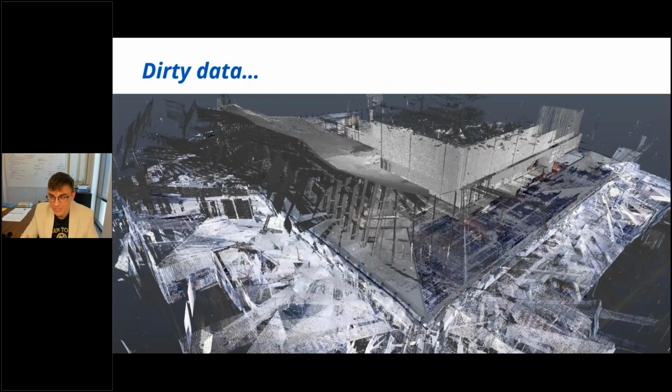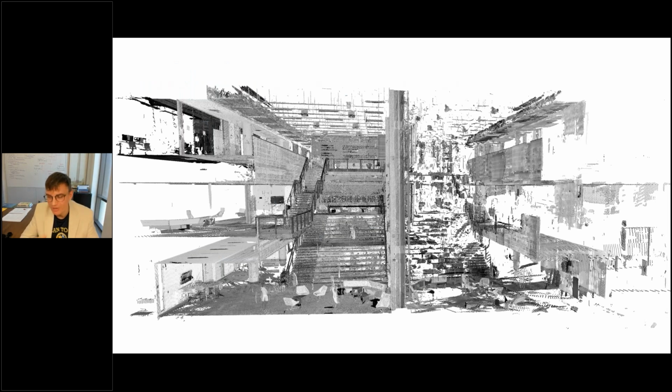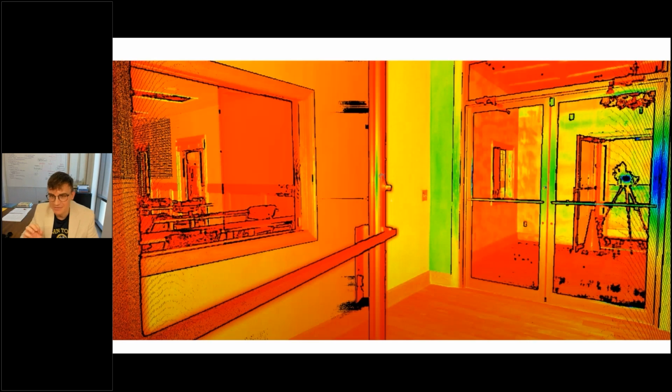If the client will be using the point cloud, you should probably spend more time cleaning it so that it's presentable. Certain kinds of reflective and refractive noise can impact registration. That's where we bring all the scans together. And so the noise needs to be clean.